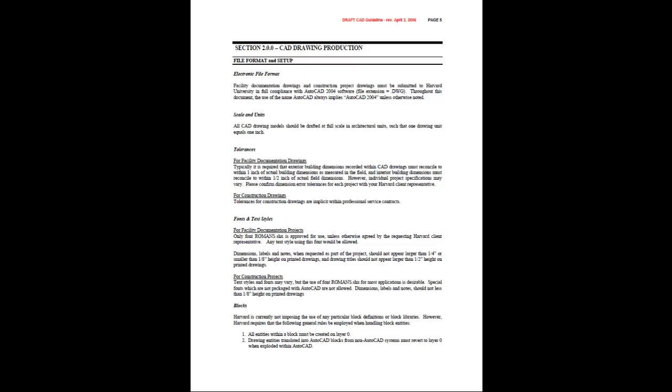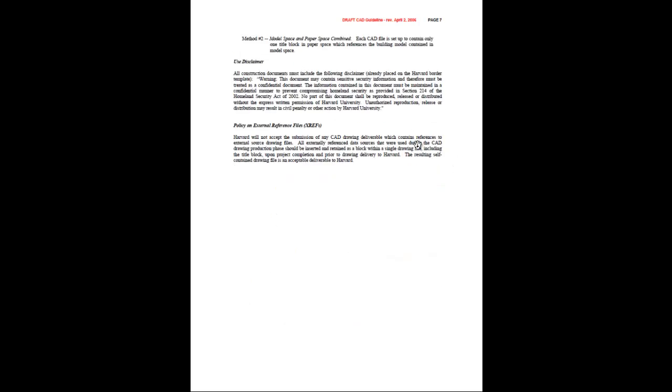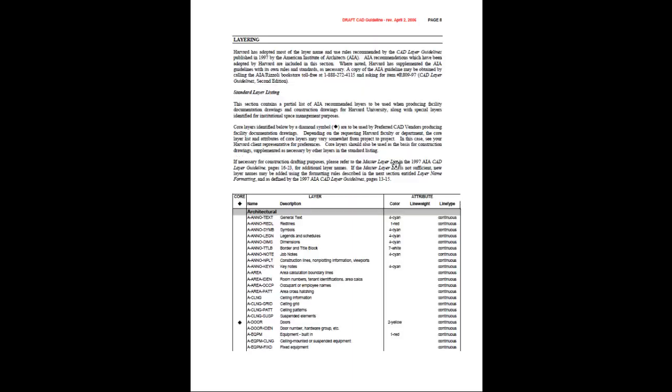When we draw in CAD, we draw everything to full scale on the computer. And then we scale it down when we get ready to put it on what's called a sheet file or a draft file. The rest of the stuff, XREFs are always a problem when we get them in ourselves because they never actually show up correctly, so it's nice that those things are all exploded.